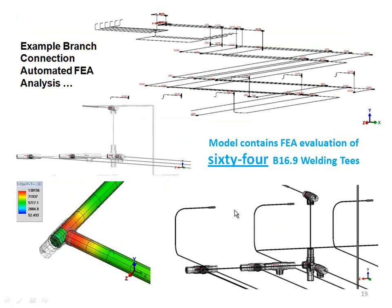Let's take a quick look at an example. In the piping system at the top, there are 64 welding tees total in two different sizes. The sizes are 4x4 and 6x4. The PCL senses that only two FEA models are needed for all the tees in this job. So the PCL runs and stores the two models in a superelement database in case they're needed again, and uses them for all 64 tees in the current piping analysis.